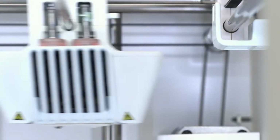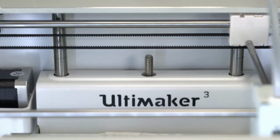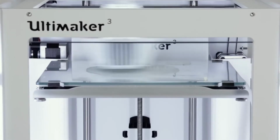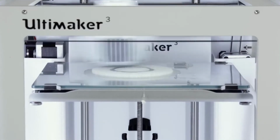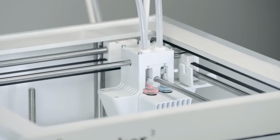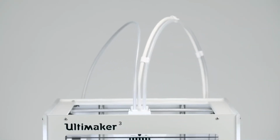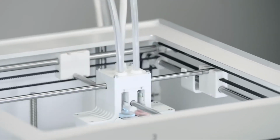Here are the areas of the interactive interface I recommend you explore for every machine before using. How to start a print job, how to pause or abort in a hurry, how to calibrate and configure your machine to use with a specific material, what nozzle to use, environmental conditions, how to monitor your print, what alerts you should watch for, and how to reset your machine for the next user.